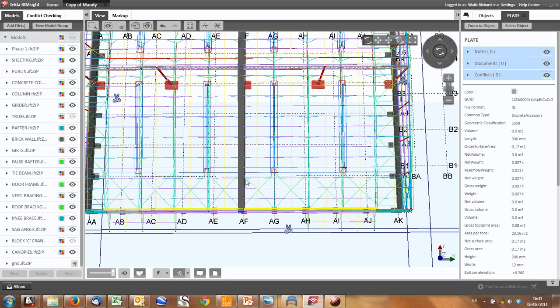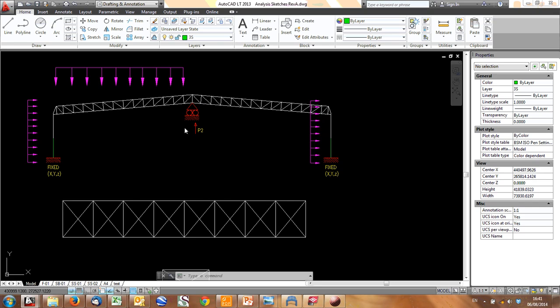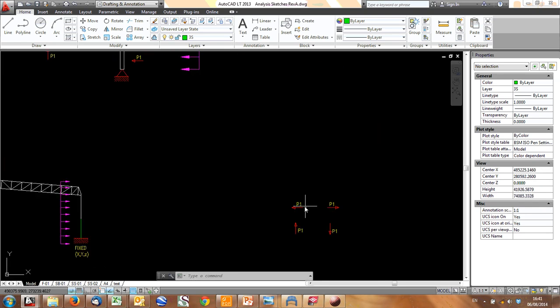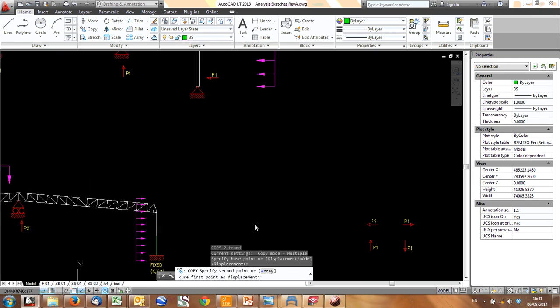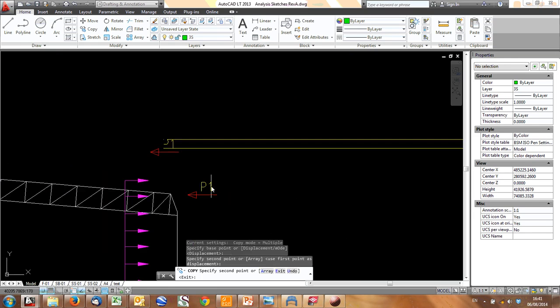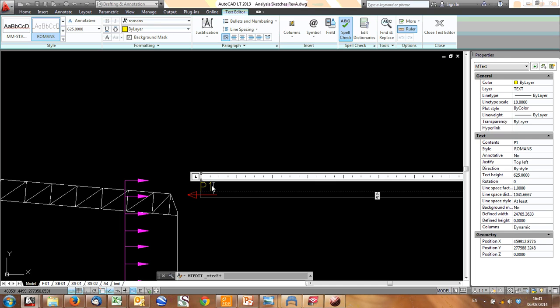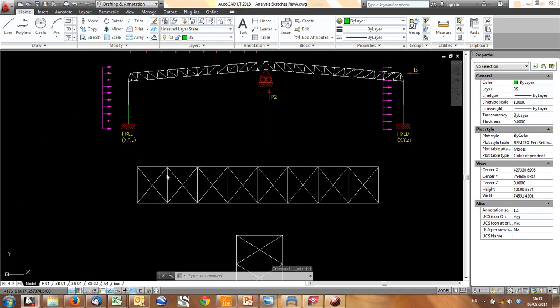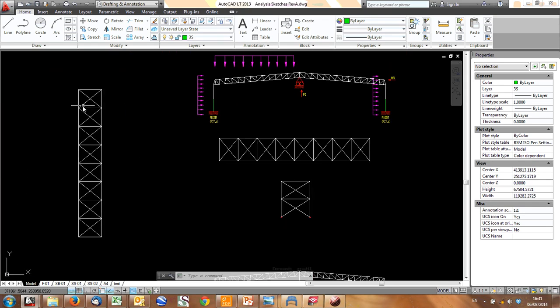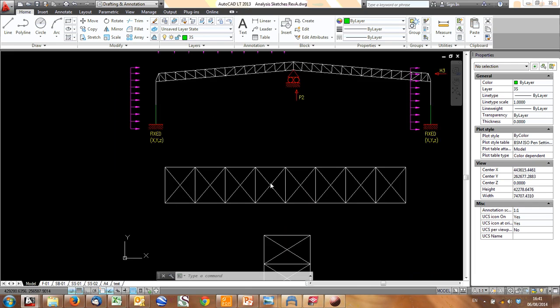And once again, where do these loads go? So now I can analyze my truss. I get a reaction. Let's call that P3 now. Maybe we'll call it horizontal load, just so you don't get confused. There we go. Horizontal 3. There's a horizontal prop. It is carried by this. This now is carried by this truss. Or we can draw it around either way.